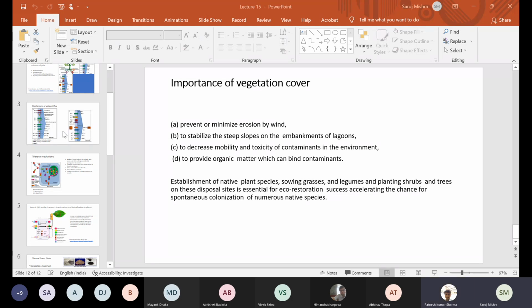Yes, ma'am, it is clear. All right. And we can see like phytoremediation is faster than microbial remediation, right? It'll be slower, but it is something which you don't have to bother. You don't have to replenish it every year, because during the initial stages, maybe the first 4 to 6 months, you may have to take care of the plants to provide them with fertilizers or organic carbon and other materials. But once the plants establish themselves, then the natural process will take over, and eventually the area can be reclaimed. However, it is going to take years for that to occur.